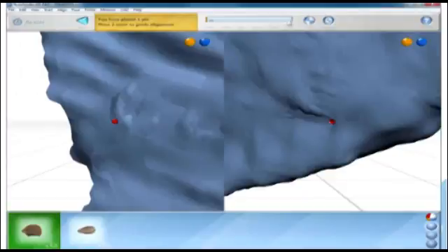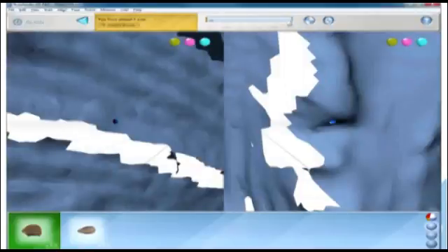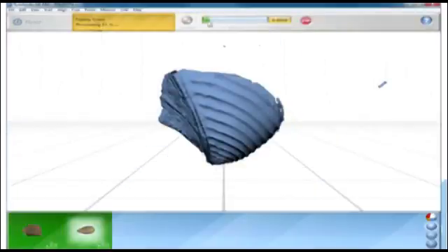It's quite difficult to get it exactly right. You probably won't be able to, but that doesn't actually matter. All you're trying to do is to tell the computer roughly how the two align, and it will then work out the best fit. When you've done the first 3 pins, you may be given another set of 3 to do if you wish, but it works fine without doing that. And here then is the model with those 2 scans aligned.